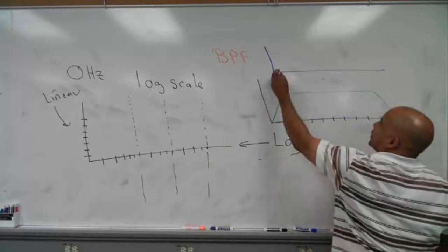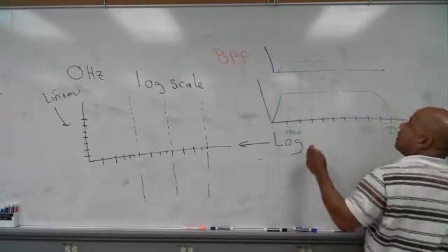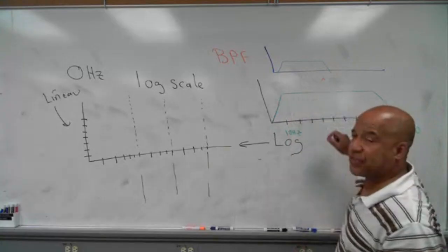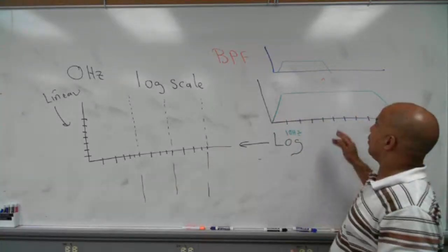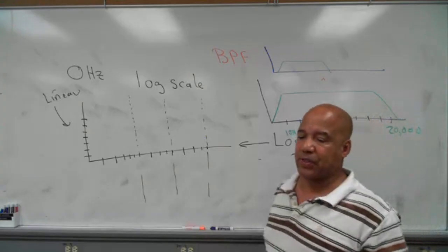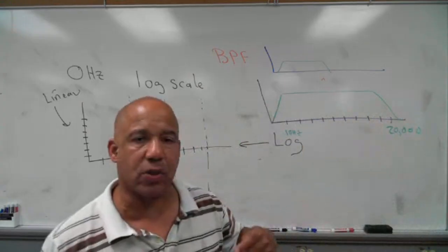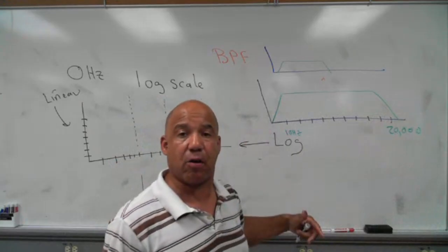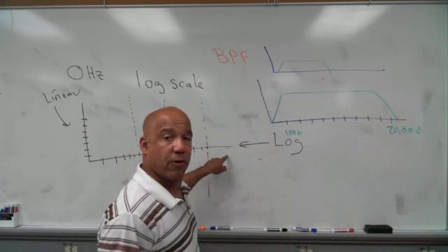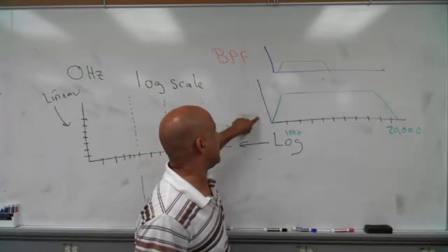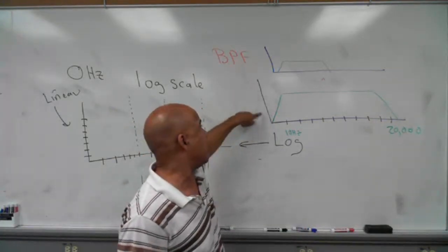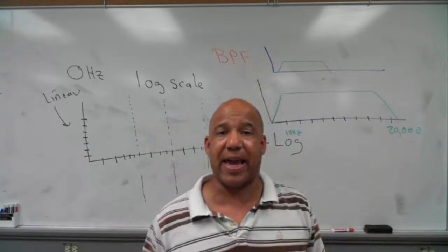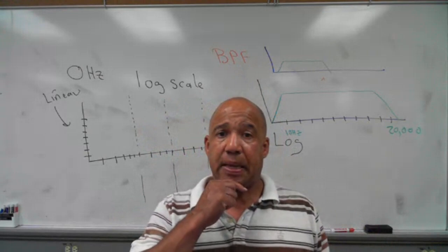The scale will be compressed, but it won't distort the graph because there's nothing changing in there. So when we do frequency response curves, typically, almost always, they use semi-log scales. They use semi-log paper. Log for the frequency and a linear scale for amplitude or whatever this vertical scale is going to be, either voltage, current, or something called gain, which we'll talk about today.